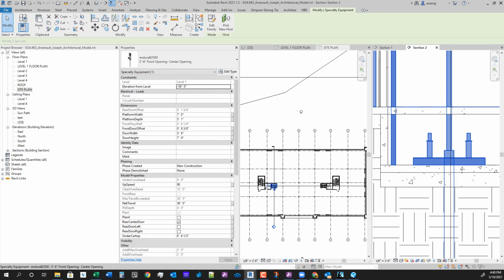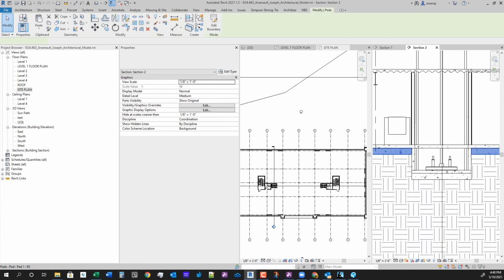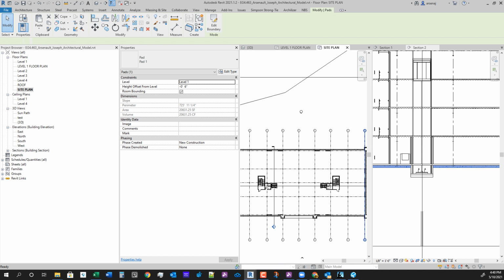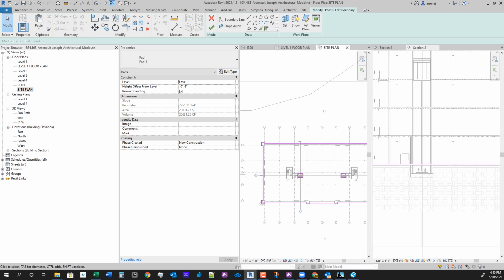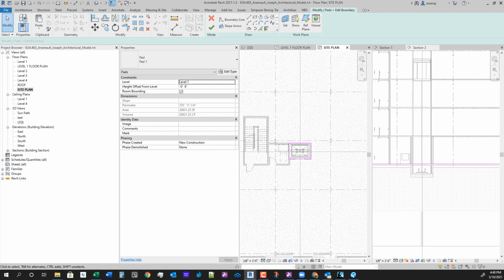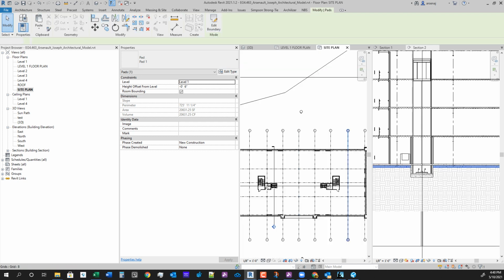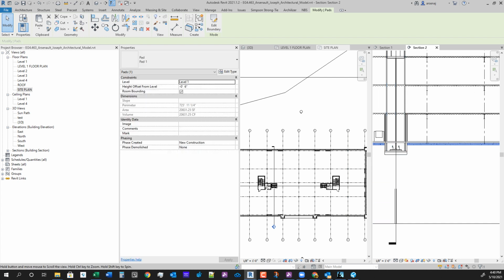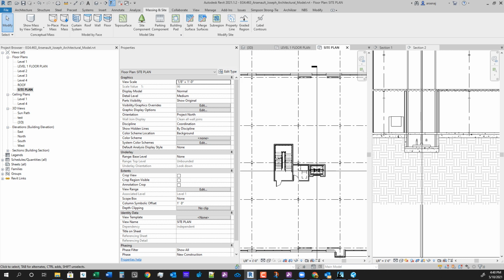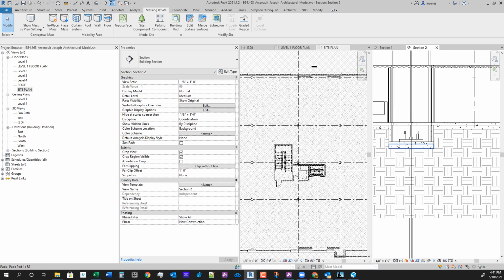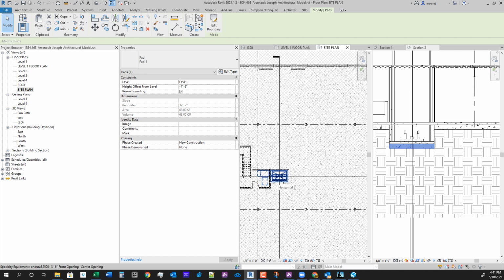So what I did was draw these building pads, which raise that up. But I cut out a hole in the center. And so here, if we select this first building pad, you can see I did the exterior of the building, but then I cut out a hole in the middle because I wanted a building pad that would be -4 feet. So then I drew a second building pad, which is here, underneath this first elevator.